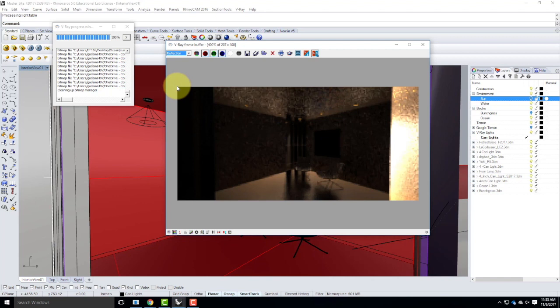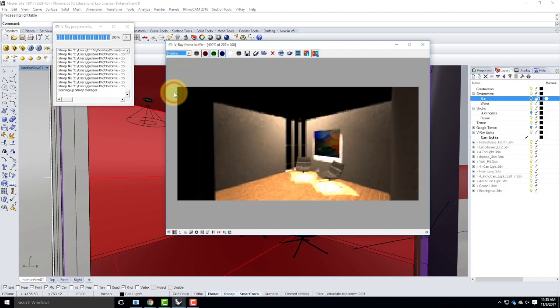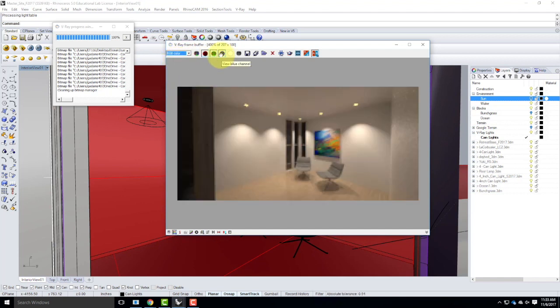Reflection would be any of the reflections, so you can see what's being reflected, where the light is, etc. The last one would be shadow, where the shadows are in a particular scene. So you've got all those pieces working together, and if you have experience in Photoshop, you can see where some of these might be useful down the road. Once I have all of these, it's worth getting in the habit of, one, turning them on, and two, saving all of them. There's a multiple save disk available up here. If you click on this, it will save all the channels in addition to your RGB, so you'll get your main one plus all your channels.